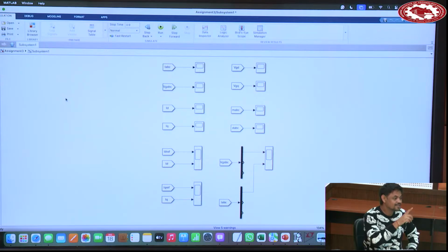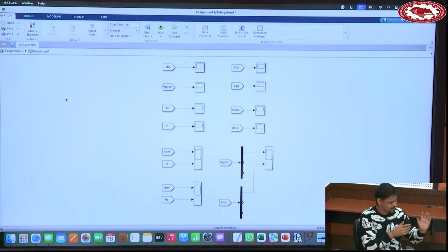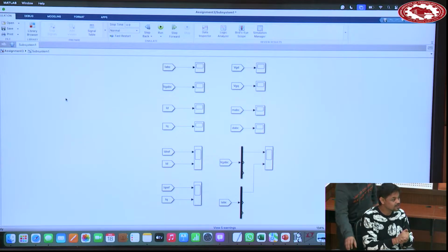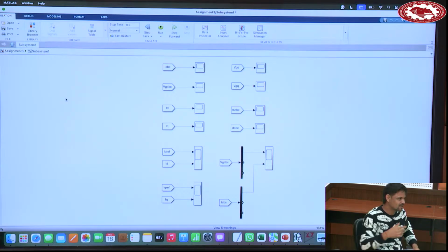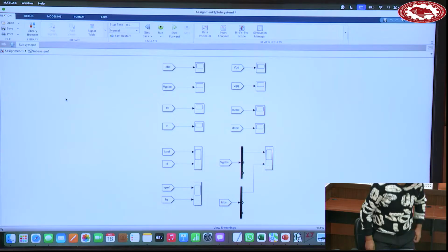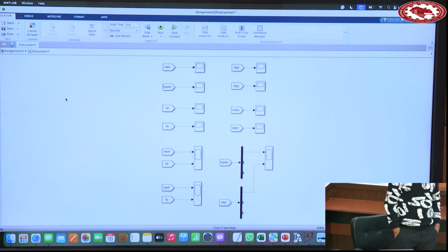And the fourth condition that leads to over modulation is reactive power. You have designed your DC link according to active power sharing. When reactive power comes into the picture, it requires more DC link. So if you are feeding reactive power, then you need more DC link. One real life example: generally inverters installed at solar power plants are asked to feed some reactive power at night time, because converters are free, there is no solar.